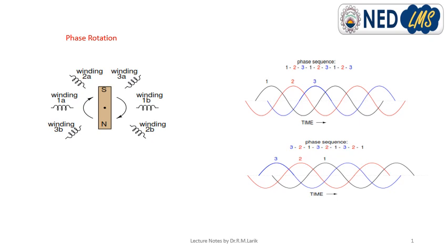The order of voltage waveform sequence in a polyphase system is called phase rotation or phase sequence. If we are using a polyphase voltage source to power resistive loads, phase rotation will make no difference at all. Whatever 1 to 3 or 3 to 1, the voltage and current magnitudes will be the same. There are some applications of three phase power, as we will see shortly, that depend on having phase rotation being one way or the other. Since voltmeters and ammeters would be useless in telling us what the phase sequence of an operating power system is.